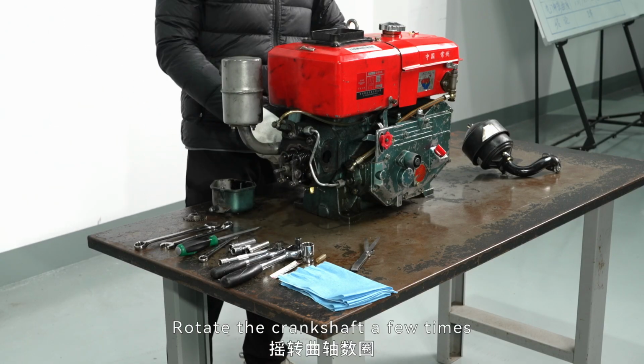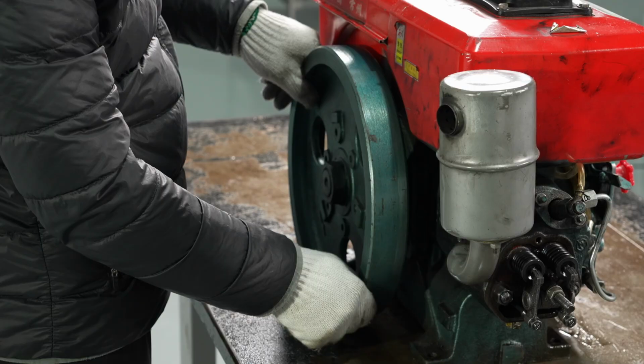Rotate the crankshaft a few times and measure the valve clearance again.